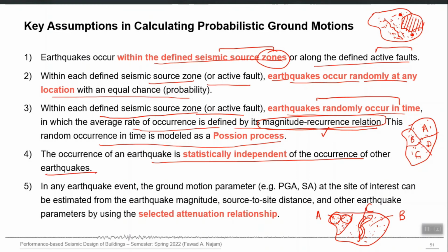As I have said, that they are statistically independent. One earthquake is not dependent on any other earthquake. This is an assumption made for PSHA. And then lastly, we can predict, this is an assumption that it is possible to predict the PGA value or